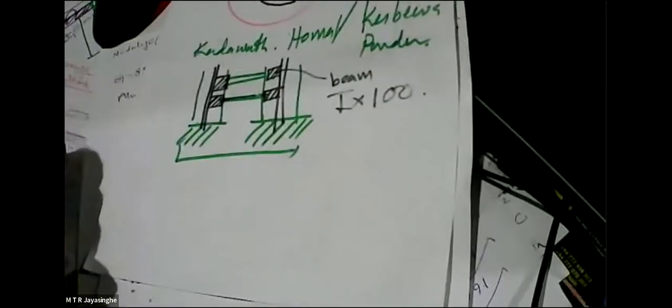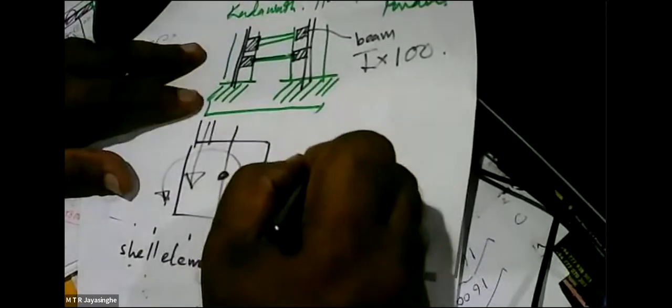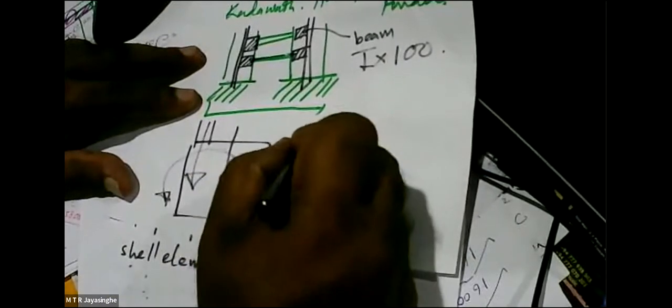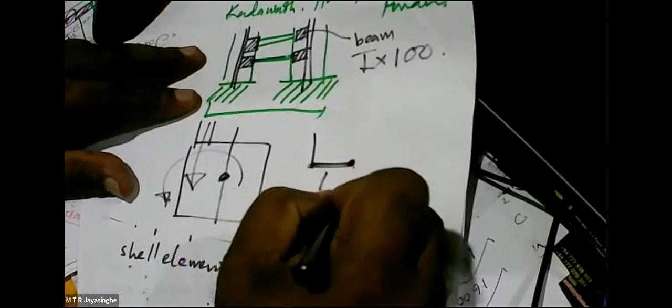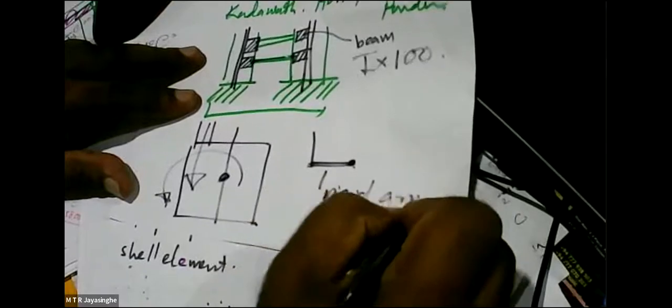And you have to learn how to use strong arms even when you are using SAP 2000, because if you have a transfer plate in the structure, you have a wall here, whereas the center of the structure is here, the wall is acting here. It can give a torsional moment. How do you model it? In the model, you model the center of the beam, and the wall is here. So to ensure that these are connected, use a rigid arm, and support the wall here.